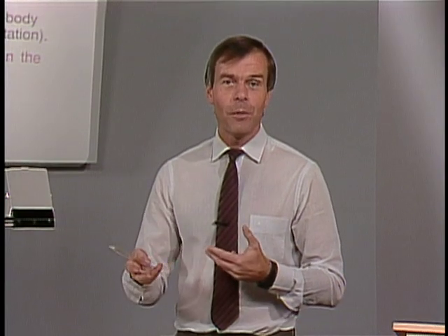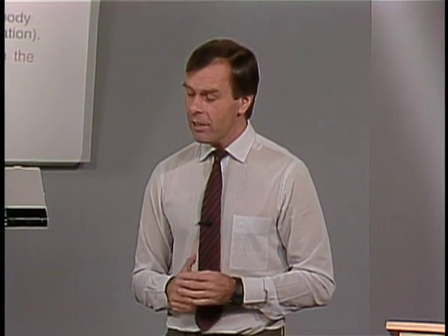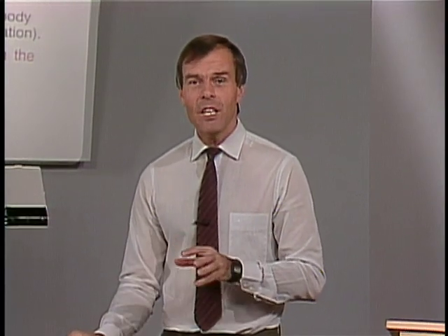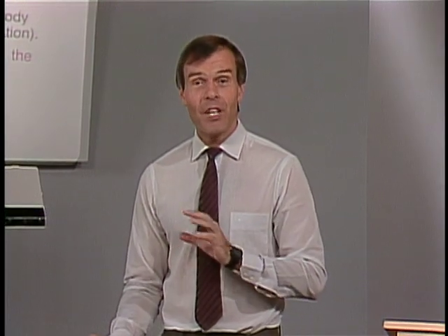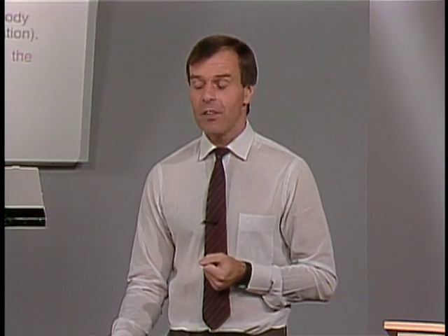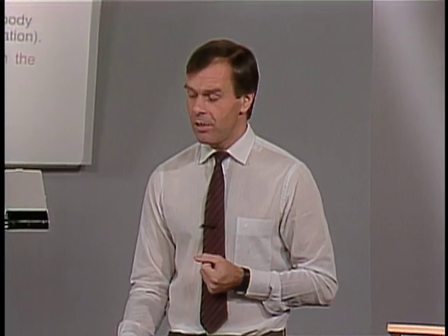We would not, in an engineering analysis, really print it out in a computer program. As I said earlier, we would, of course, want to have the Cauchy stress as the stress measure with which we want to design our structure. I look at it as a measure that is convenient to work with in the engineering analysis. It's interesting, of course, from a theoretical point of view to look at the elements and to see how large or how small they are when compared to the Cauchy stress, the real physical stress that we're interested in. But we don't really need to look for a strong physical interpretation.